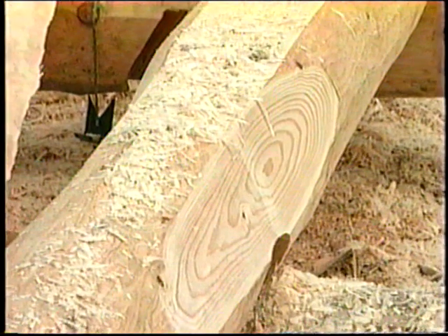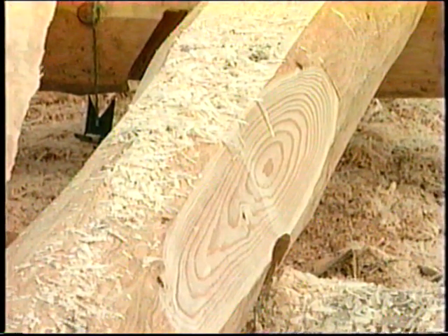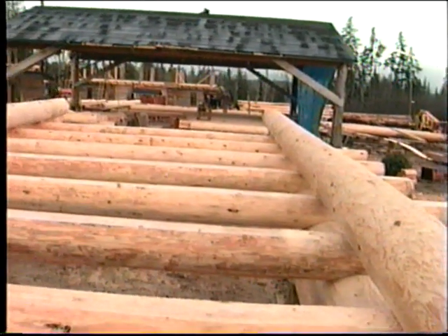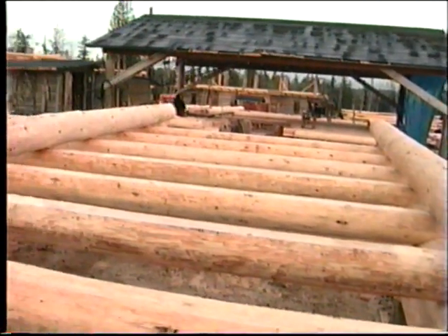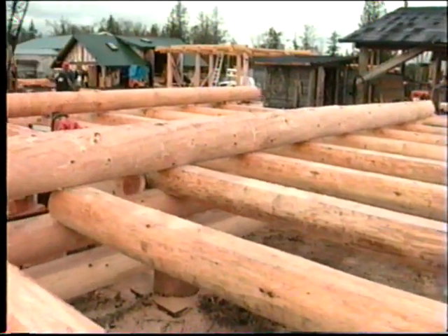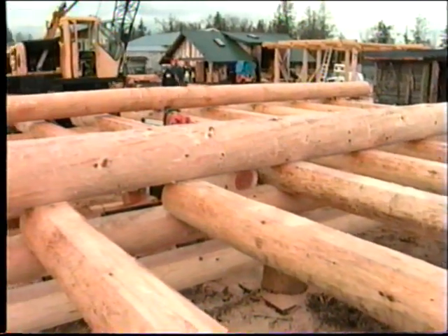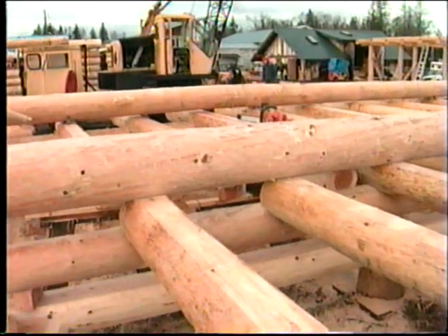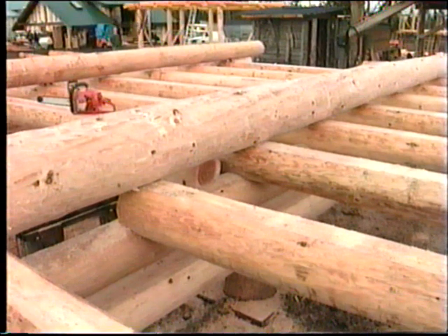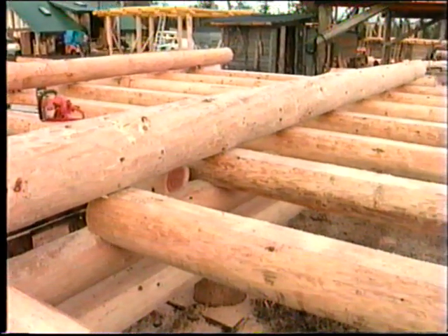Use good, clean, straight logs for this position so that you can get a scribe line that is easy to see. The multiple notches in this log will test the skill that you will have developed as you built the walls. Work very hard to obtain the required fit on the first operation, because adjusting and refitting this log can become a little frustrating.